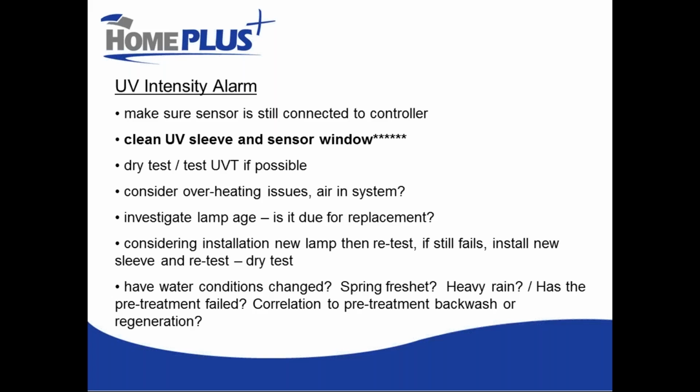I have this bolded for a reason. Clean the UV sensor window. And honestly, if you still have an alarm problem, clean it again. Be really, really sure that you've got the sensor and the sleeve clean before you move on to any other testing.